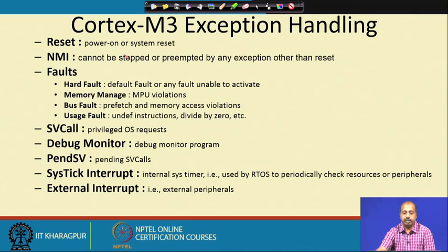As far as the exceptions are concerned, reset is there, that is power on or system reset. Then the NMI, non-maskable interrupt. This cannot be stopped or preempted by any exception other than reset. So, that int NMI line is there, on which you can connect some non-maskable interrupt.